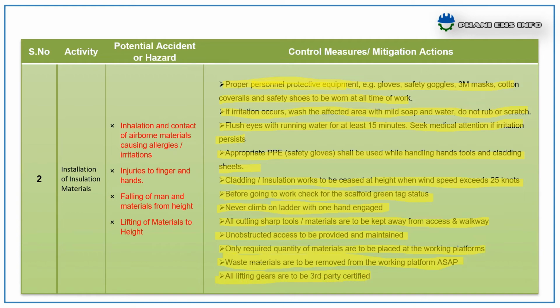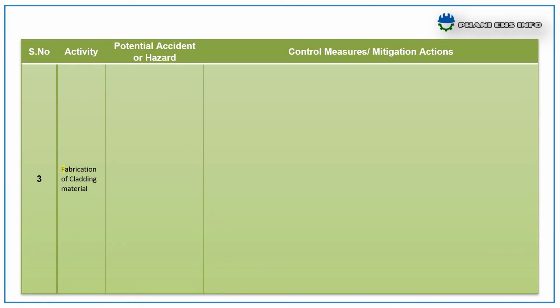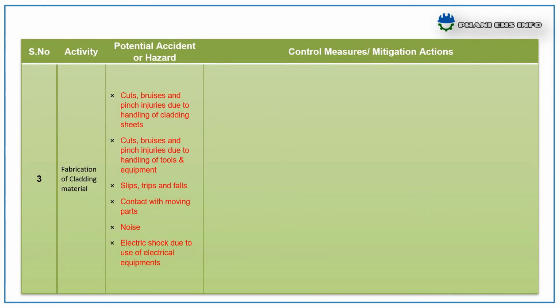And the last activity, fabrication of cladding materials. Here the potential hazards are cuts, bruises and pinch injuries due to handling of cladding sheets or due to handling of tools and equipments, slips, trips and falls, contact with moving parts, noise, electrical shock due to use of electrical equipments.